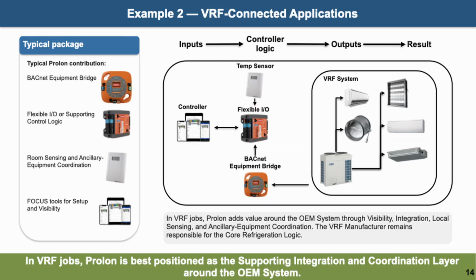This example requires more careful positioning. In VRF-connected jobs, Prolon is best positioned as the supporting integration and coordination layer around the OEM system. Prolon is not typically the core controller of the VRF refrigerant system itself. That remains with the VRF manufacturer. Prolon can add value through the BACnet equipment bridge, flexible I/O, or supporting control logic, room sensing, ancillary equipment coordination, and Focus tools for setup and visibility.